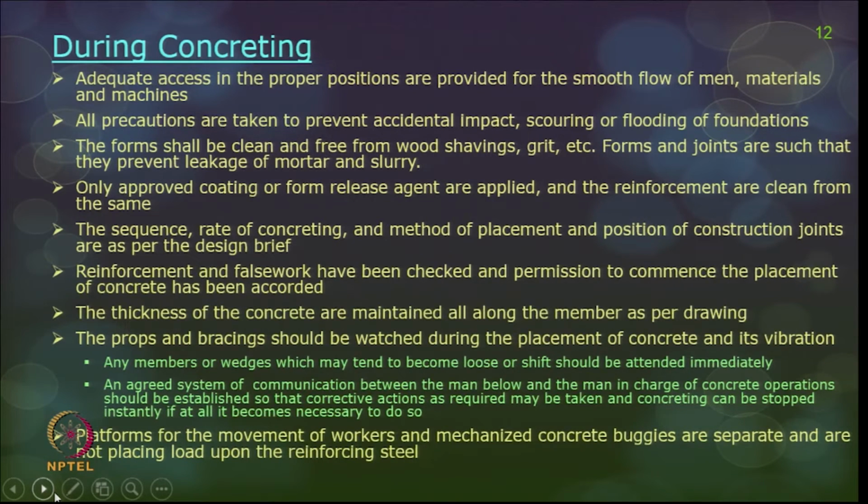All precautions should be taken to prevent accidents in terms of flooding in the foundations, that also should be taken care of. The forms should be very clean and free from any wood shavings or dirt, grit and so on. Maybe the earlier concrete which is available on the formwork, everything should be cleaned up when the formwork is in place, because it may affect the strength of the concrete.